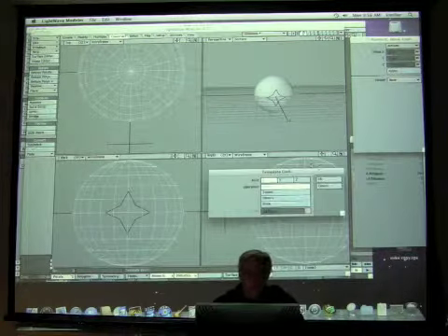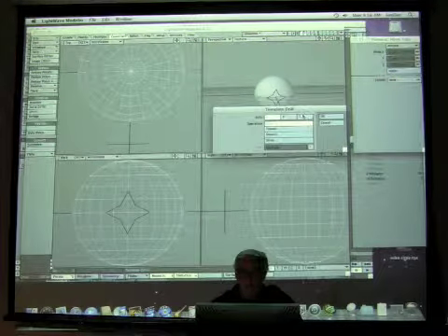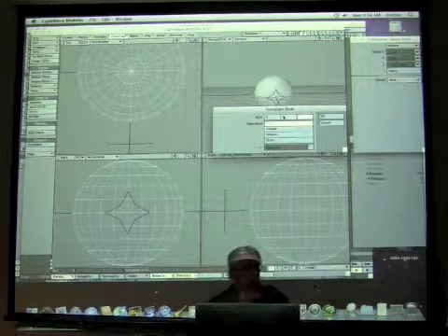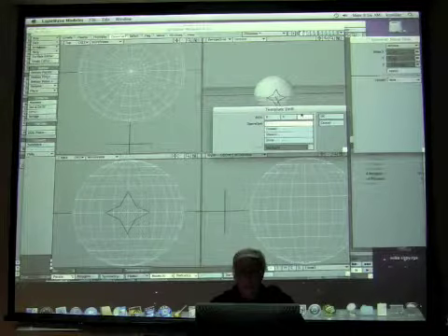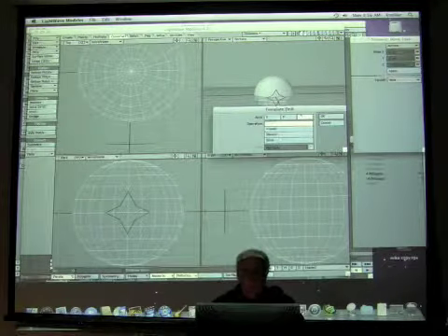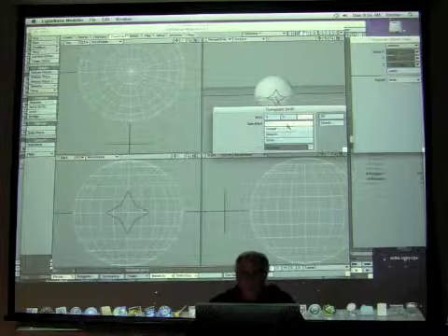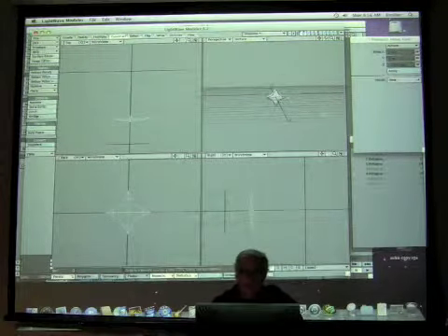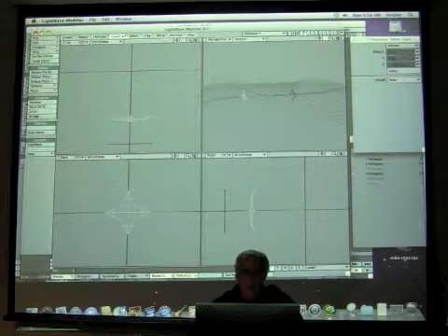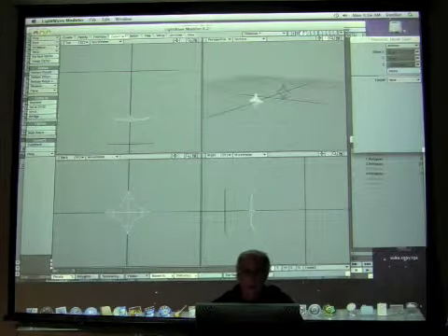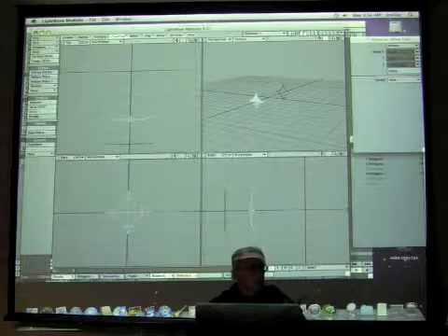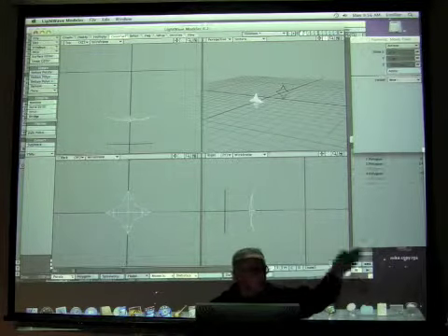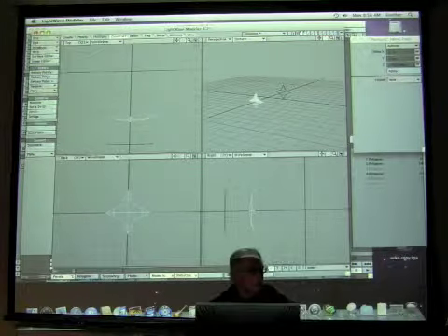So let's go ahead and select drill again. I want the z-axis. If I select X or Y, you won't see anything happen because it'll just cut along those axes. And it cuts all the way through. And you have 4 choices. You can core it. It's like you core an apple, and you can see what's left. You're left with a core. You're left with a star shape on either end. And if you want, you could use the skin tool, and you could stretch those, connect those together, and you have a nice little curved ends on either side.